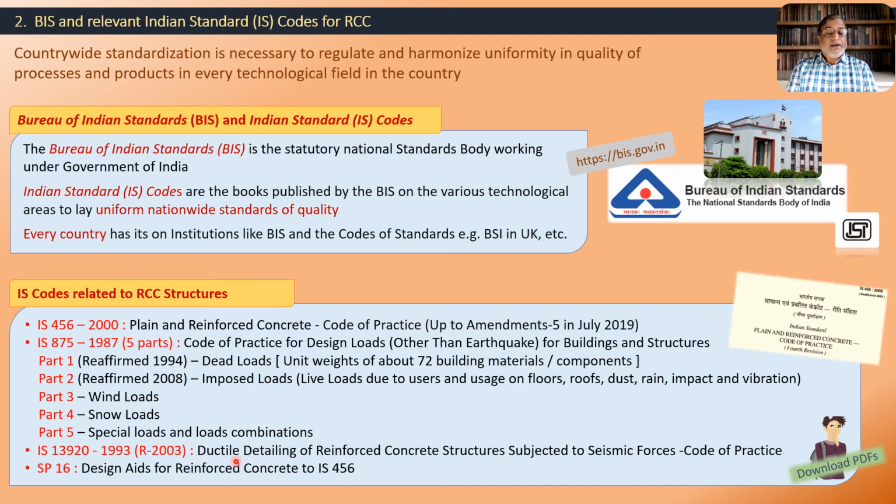So ductile detailing for earthquake is specially considered in IS 13920. Otherwise, IS 456-2000 is already giving us various rules and laws for the detailing of reinforcement. But ductile detailing for seismic forces is to be considered again separately. So we have to take help of this IS code also.